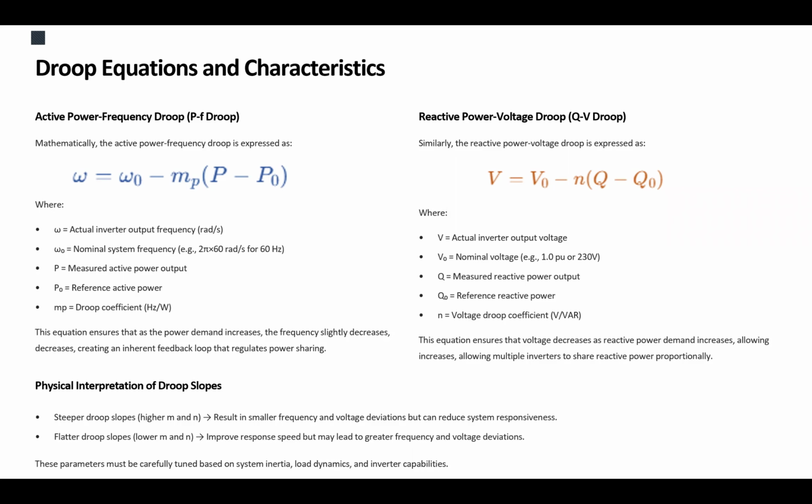Now this is actually a very good point, because I wanted to mention in parentheses one of the biggest regulation rules that exist, and one of the rules that prevent the increase of renewable energies. If you want to add any resource to the grid, you have to run a full analysis over the grid: transient, power flow, reliability, stability, a full analysis of how that resource would change the dynamics of the grid and how it would affect other utility owners.